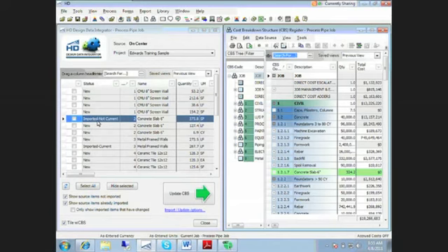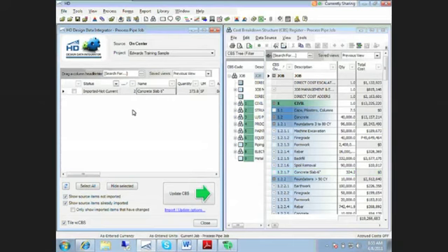This is a typical register, so you could set up views. For example, you might want to have a view that's just set up to filter, show me everything that's in the estimate but not current. Right. So as we change our on-center takeoff, anything that's in the estimate but out of date now would just show up. That's all we'd see in this window. Okay, so you can use the column filtering, saved views, just like we do on any other register.